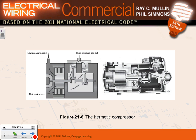I don't know if you can see. They take the gas over here, and they circulate it over the windings, high pressure gas. It cools the winding as it goes out. Now, designed by the manufacturer, the low pressure gas circulates over the windings to cool it. As it enters the compressor, it goes over the windings, and it cools it. Can you see that, Jeff? That's all you need to know. It cools the shaft, the windings, the bearing, and so forth.